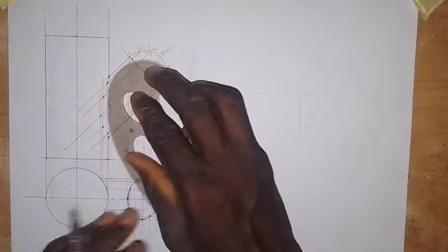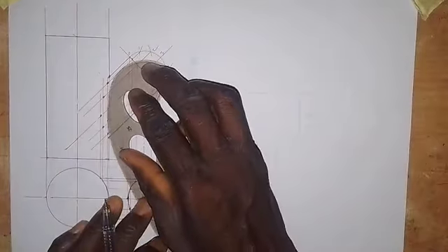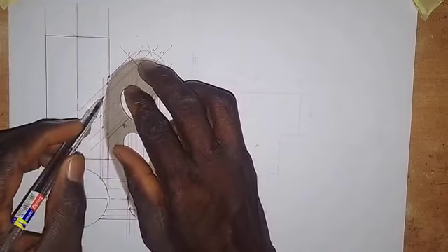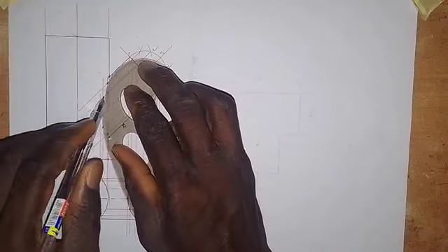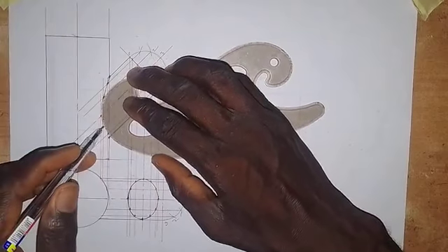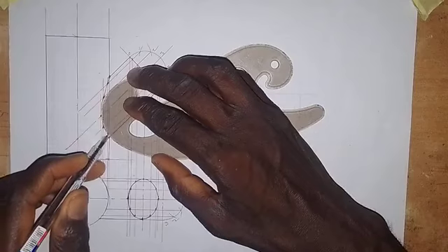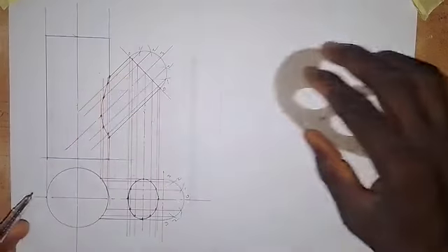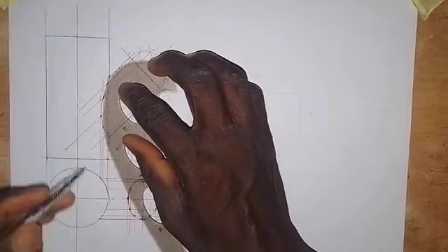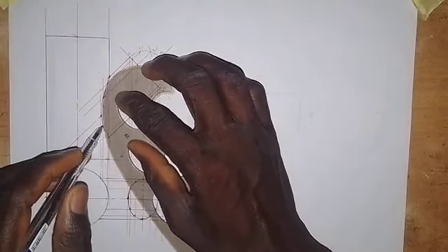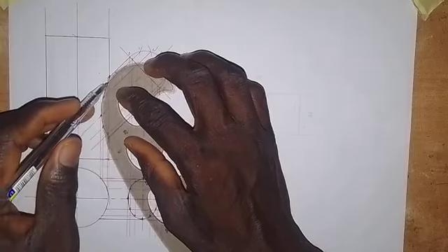So what we do now, with the French curve being set along this point, we need to make sure the curve comes out very well. So I will join this point together like this. Okay, then at this point, I'll just turn, then we can join these points together. Okay, then coming down here like this, we join them together like this. So here we have the curve of intersection, as you can see here, or curve of interpenetration, as you can see it here like this.